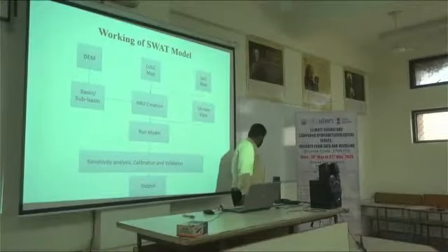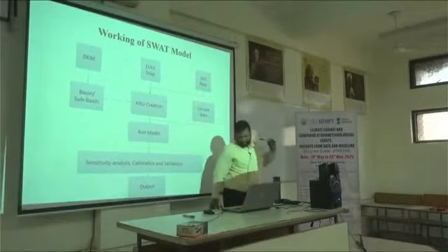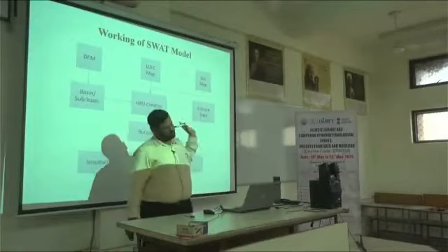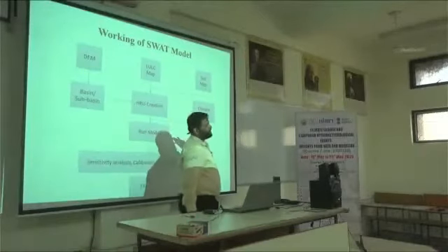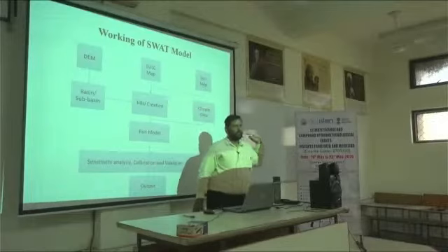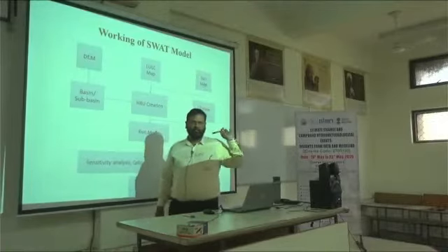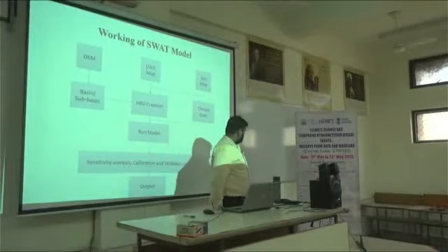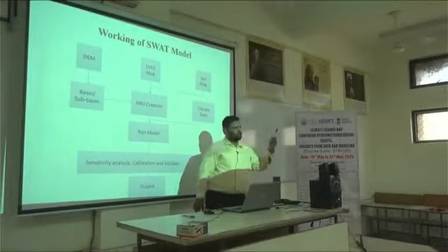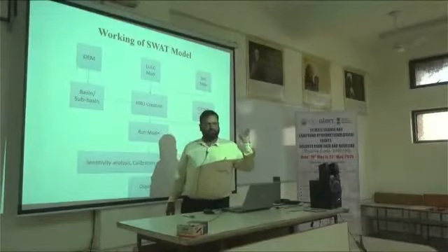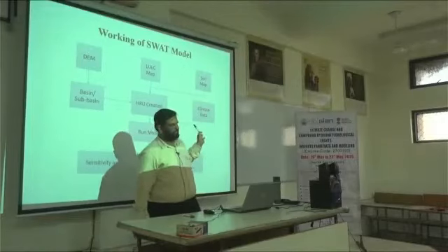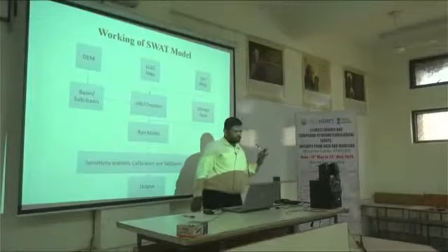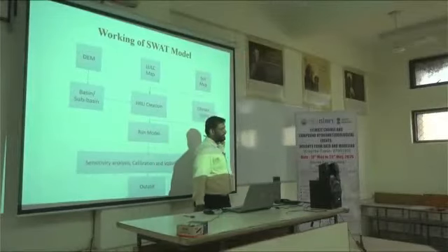Sediment concentration data can also be used. If you are interested in sediment concentration, SWAT also provides sediment concentrations, in milligrams per liter. Or if you are interested in load, then you have to convert your observed data into load. You have to multiply it with velocity and some coefficient so that the concentration data is converted into load. So these 5 types of data you require.